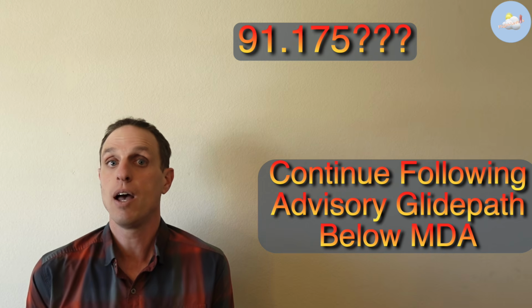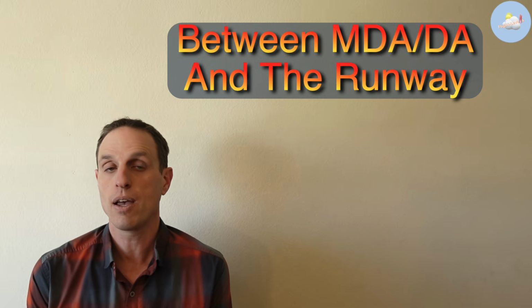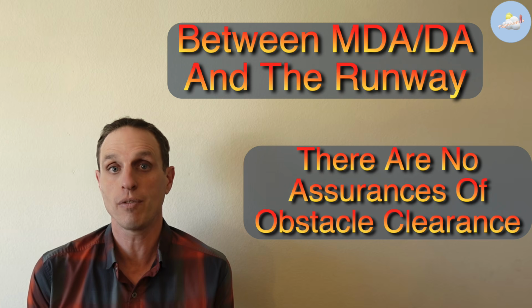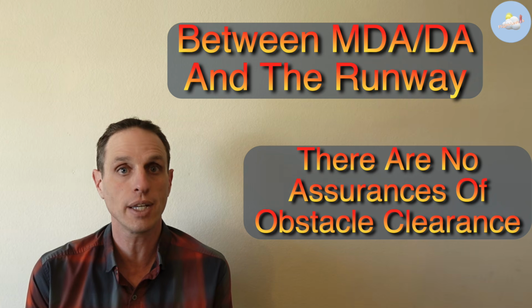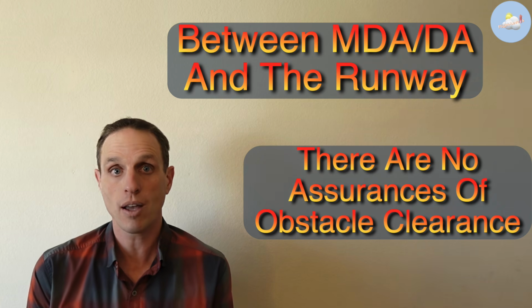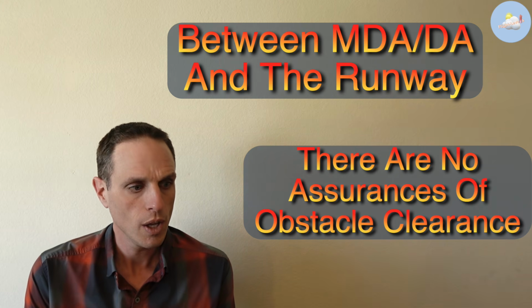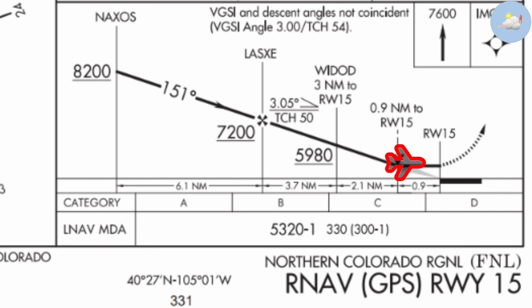below MDA, understanding that just like any approach between the MDA and the runway, there are zero assurances of obstacle clearance. That is completely up to you. And that also includes below decision altitudes. Also, you do have the prerogative to enable altitude hold and continue flying at that minimum descent altitude all the way to the missed approach point.